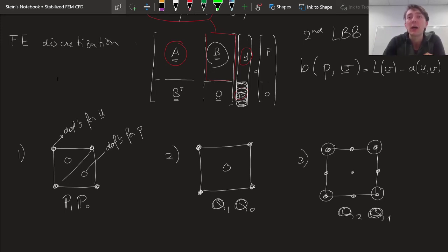I'll give two different types actually, because I think that's instructive. One of them is going to be that I'll show that for a given pressure, I actually do not change my result after I multiply B with P. So the result is independent of the addition of this one pressure field, and that's called a spurious oscillation. That's a zero energy mode.